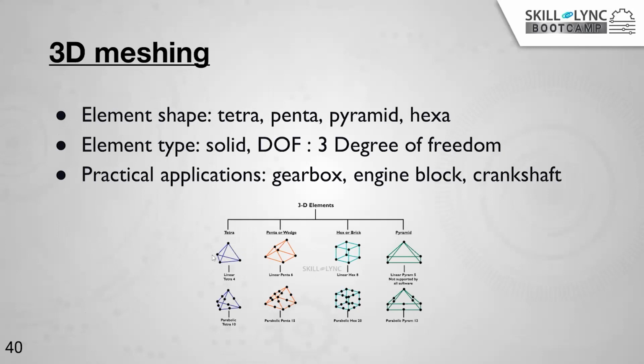This is tetra. It's a 4-noded element for linear tetra. Higher order tetra is a 10-noded element. These are penta, higher order penta. Hexa or brick. This is a linear order brick.